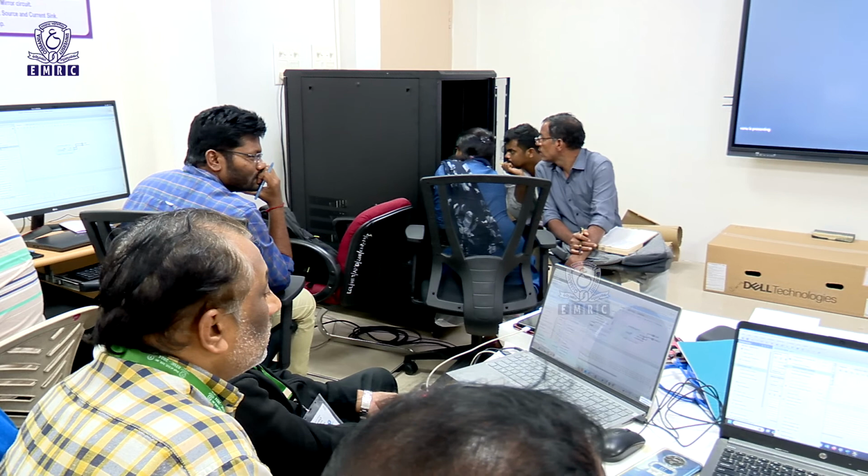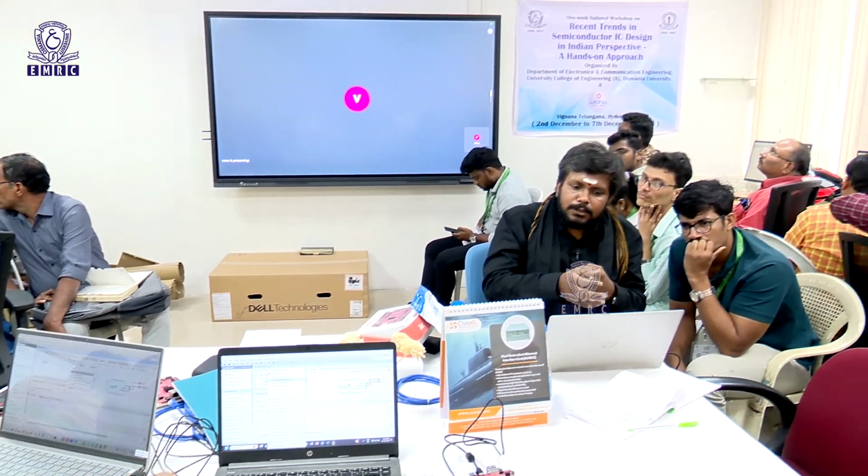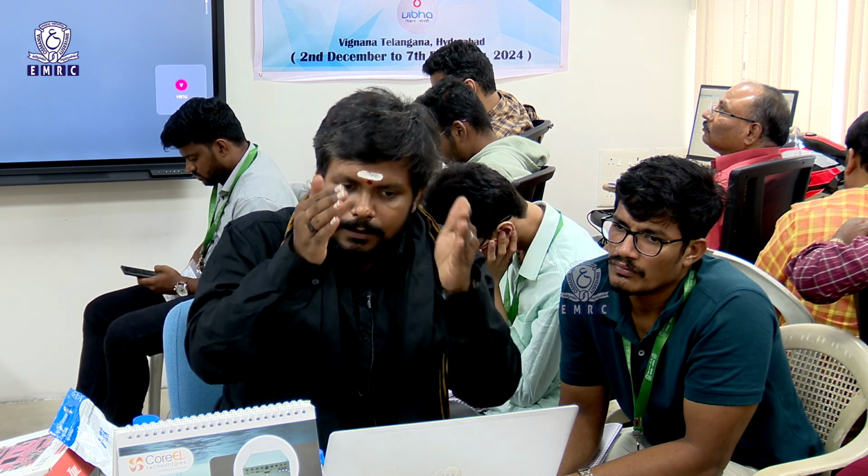Why is it important? Because we already have a pin planning assigned to this particular IP. In the first half we saw how we design and only talk about the ports in the design, and we need to give manual connections to the package pins. But when we are using IPs, those connections are already made. We don't need to manually assign them again, but we need to take care that the logic is not the most important at this point. Those connections need to be solidified. Okay, that is what generate output products is doing.